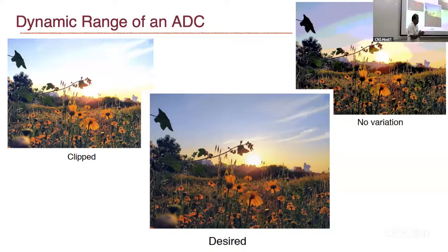More the better, but depends on your application, of course. And we talked about dynamic range, and your ADC's dynamic range should be greater than your signal's dynamic range. Okay, those are the three things. Now, another important aspect I want to cover from next slide onwards is the power consumption, which is again very important.